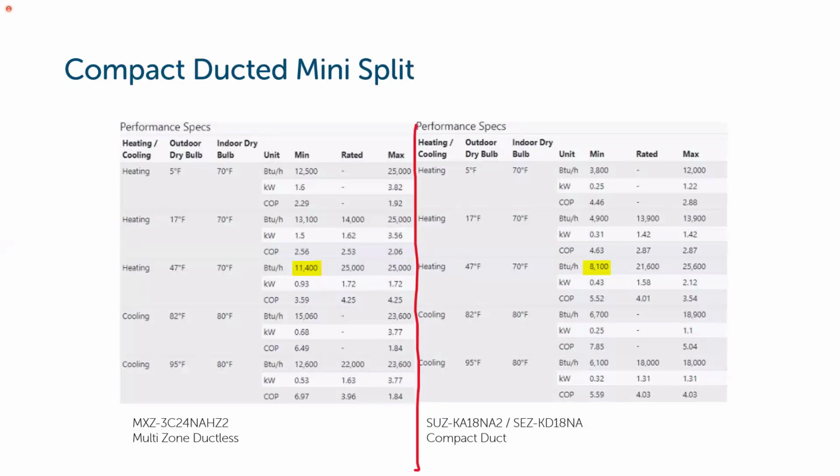One of the things to briefly show here on the performance side of things. Knowing your room by room load calculation is crucial for good design, and that goes for whether it's going to be a forced air system or a hydronic system. Knowing what each room needs and knowing that you're adequately supplying that room is crucial.